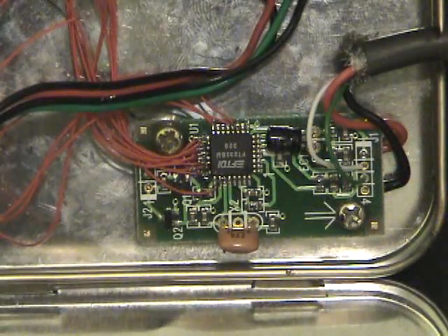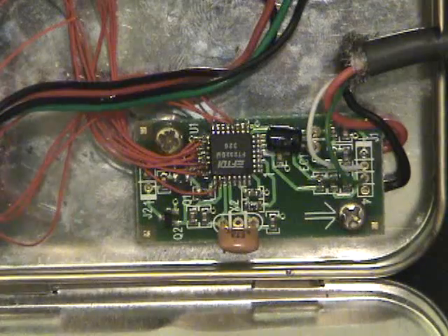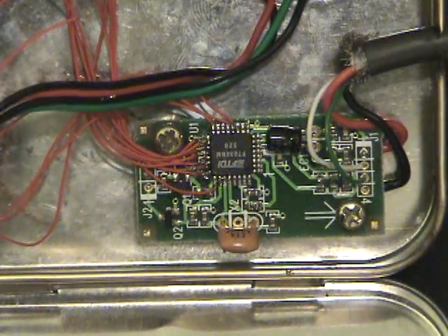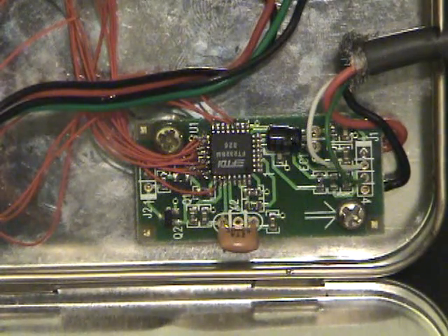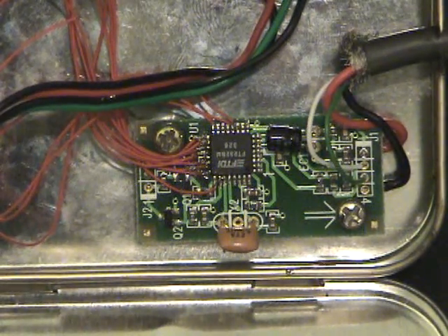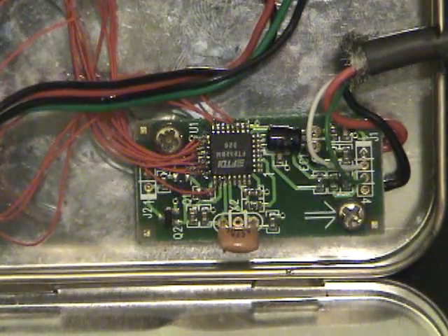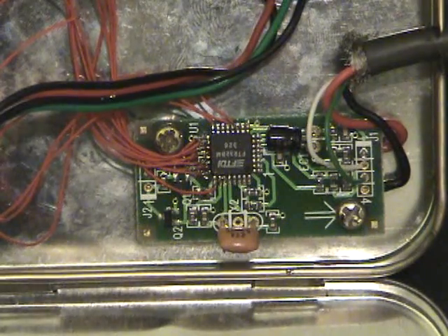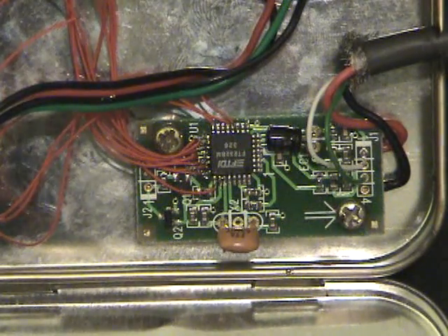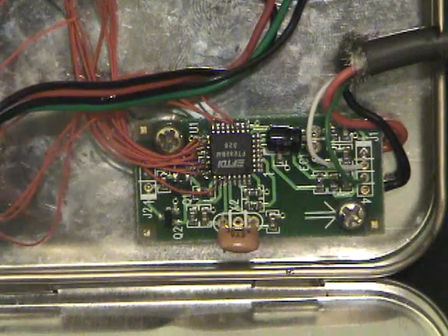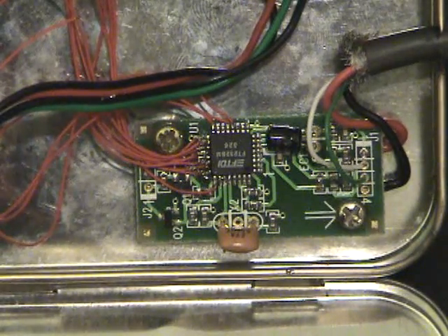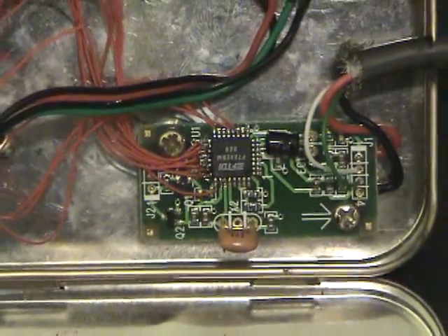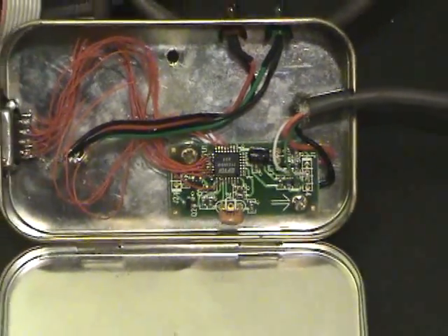What you are seeing here is actually a rewired FTDI 232 controller. What I like about this chipset is that it does all of the level voltage converting for you. You don't need to do any of the Max 232 or the Max 3232 level conversions. There are other forms of level converters that you can use, but the Max 232 and 3232 are the main chips to be using if you're using any kind of serial communications. This actually used to come out of an old, I think, cell phone or amateur radio programming cable.